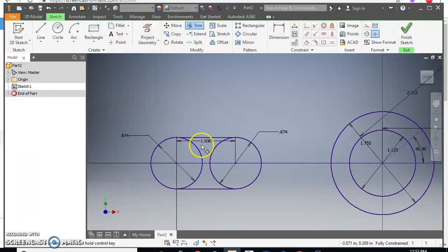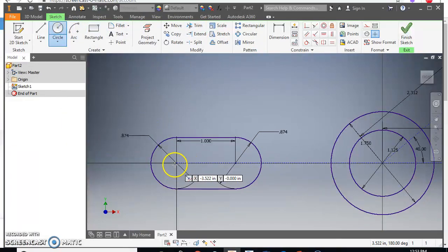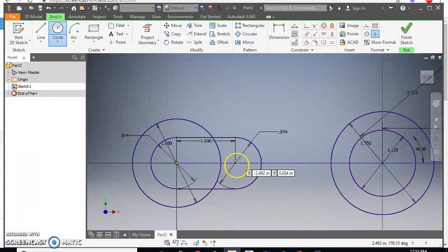Let's get the trim tool. We'll trim out the insides portion of those circles, so now we've got the arc set up the way we want them. We'll do the exact same thing here with the outside. So the larger circles, we've got a radius there of 3/4 inch. I can figure that in my head. That diameter would be 1.5. Two of those.